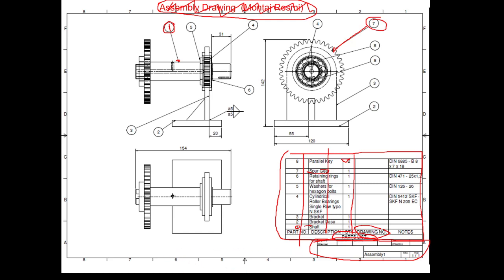As I said, for non-standard parts, there must be a drawing sheet. For each non-standard component, there must be a technical drawing, a detailed drawing. So physically, after printing, identify that detailed drawing sheet. But for standard components, since there is no need for engineering drawings, because in the library someone can find the document published by the Standardization Association, this column will be empty. Do not fill in the column because there is no drawing sheet.